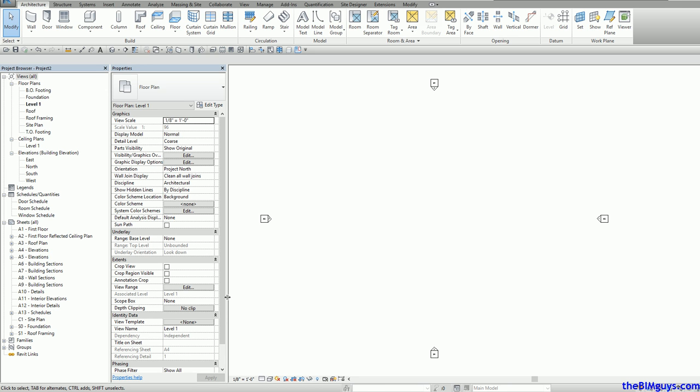It's all right. Yeah. So what we need to do when we're working on projects, so this is kind of the game plan. We're going to build different buildings, and then we'll bring them into the master, and this will be your master RVT. And you can link them in. If you're an AutoCAD person, if you ever used XREFs before, okay, well, an XREF is a link. You link these in. So you could work on this building. Let's say you added a tower off the backside of this building. You hit save. When you open up your master, boom, there's a tower on the master. So you have these buildings, and you'll have your master that links all these in.